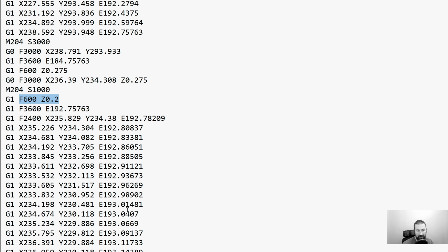This is what builds this visible seam, this Z seam. This comes from the Z steps. And this also eliminates any possibility for non-planar prints, which a normal 3D printer is actually capable of. Of course, you have restrictions with nozzle clearance, and you can hit the part itself. So fully automated non-planar printing and slicing is actually quite hard if you want to fully automate it.